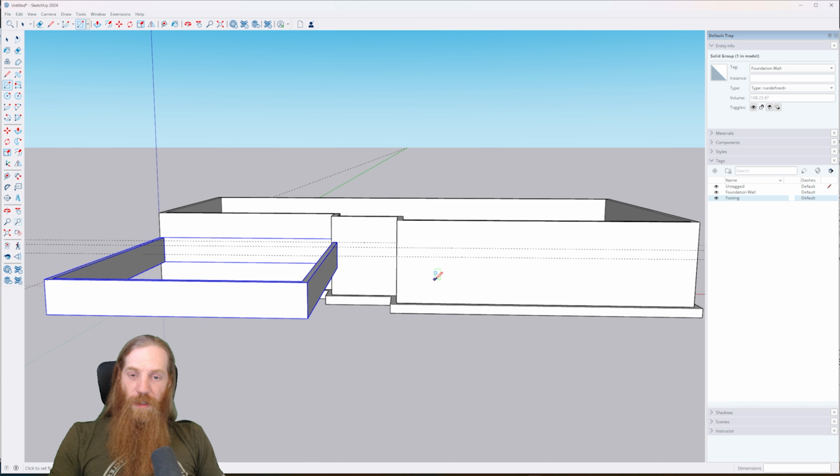So in the interest of longevity for our building materials, we want concrete to be the material that the snow piles up against more. Therefore, having exposed foundation for the first few feet of the exterior walls of the home is going to be a lot better in a high snow environment than having just 6 to 8 inches of foundation wall above grade, and then your framing begins and you have siding and all that, right?